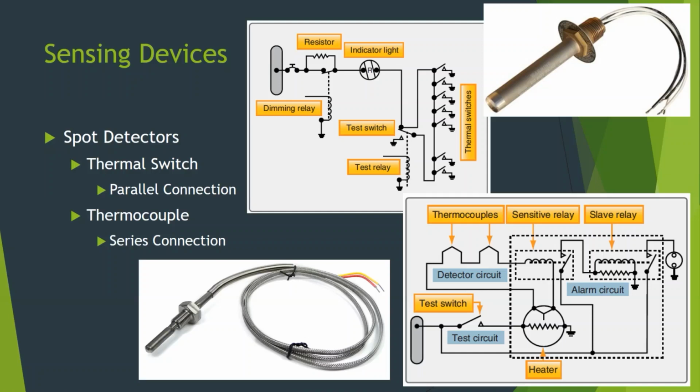When we had one of those bleed loops fail, we hoped and hoped and hoped it was one of the ones back in the aft equipment bay. But 9 times out of 10, it was one of the ones under the cargo floor or under the passenger floor. If it wasn't in the tail, we hoped it was in the cargo bay, because then we just pull up floor panels. If it was under the passenger floor, now we have to remove seats, we have to remove carpet, and then we can start to remove the floor panels.